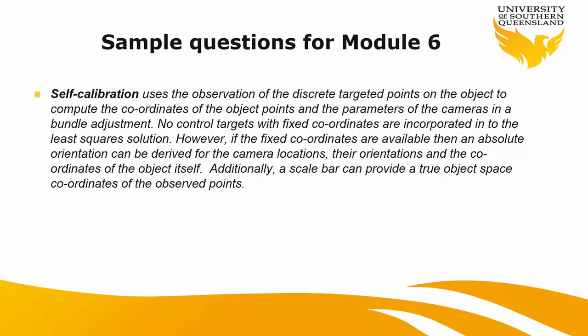We have a self-calibration, which you need to do beforehand, yeah? Usually for the type of work we're doing in surveying, we do self-calibration. Why? Because our object is so big. How are you going to put the coordinate frame in front of the dam, yeah? Or in front of a bridge, yeah? Is it possible?